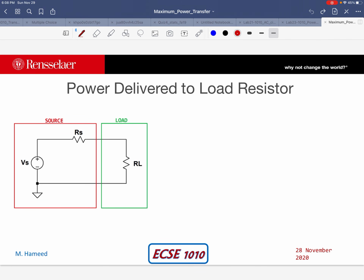For the sake of computing this power, I'm going to assume that I have a current Is that is coming out of this voltage source, and this current is going to be the same for both Rs and RL because they are both in series. Now I can easily find this current by using Ohm's law. I can write Is as Vs divided by the sum of the two resistors, Rs plus RL. That's going to be the current that is supplied by the source to the load.